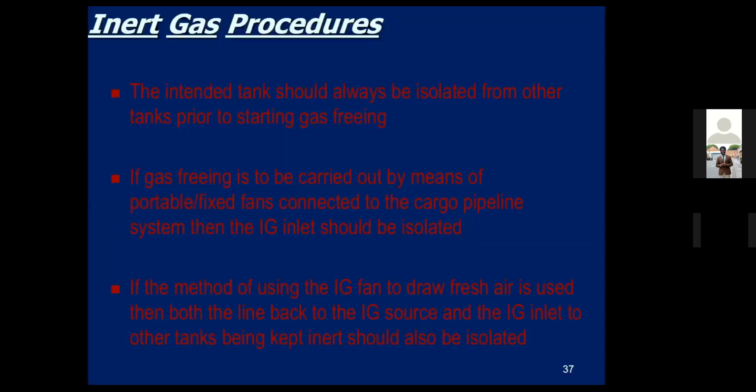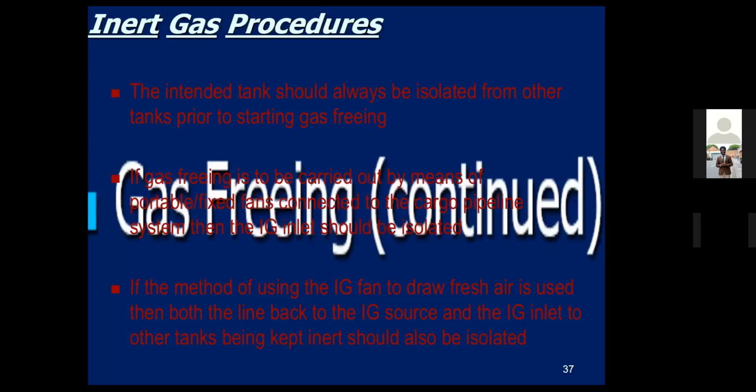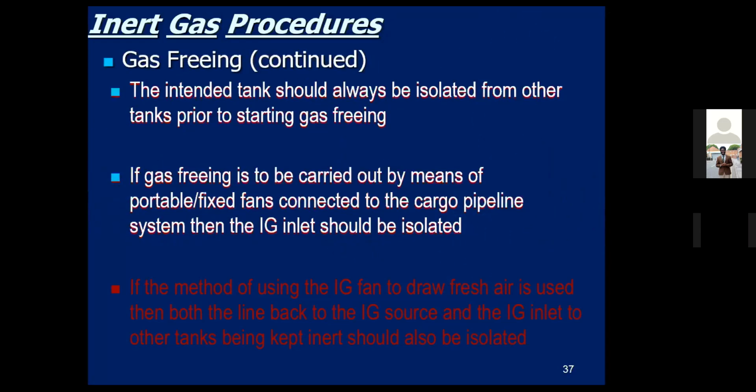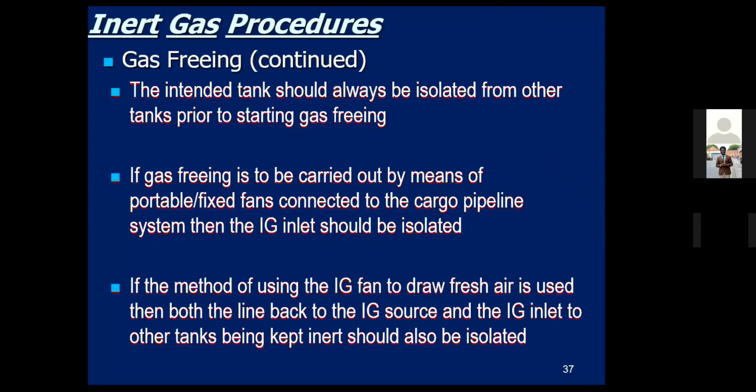It's not just about saying, okay, this is the gas, but you have to follow the procedure. For instance, when we talk about the critical dilution line, you need to purge the tank first, ensure that the hydrocarbon content is below 2% that will support combustion. So it's very, very important.